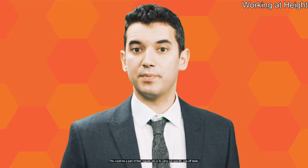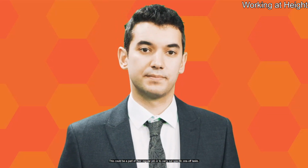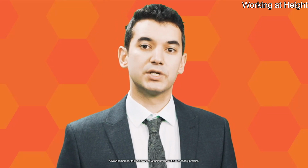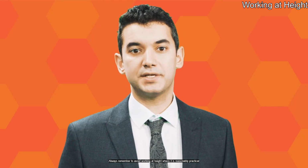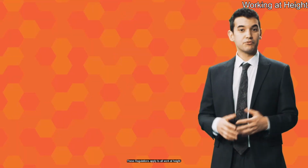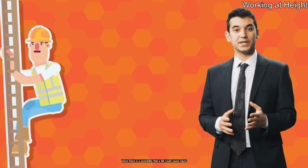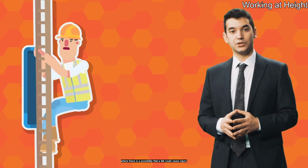It is quite common for employees in the construction industry to, at times, be asked to work at height. This could be a part of their regular job or to carry out specific one-off tasks. Always remember to avoid working at height where it is reasonably practical. Do as much work as possible from the ground. These regulations apply to all work at height, where there is a possibility that a fall could cause injury.